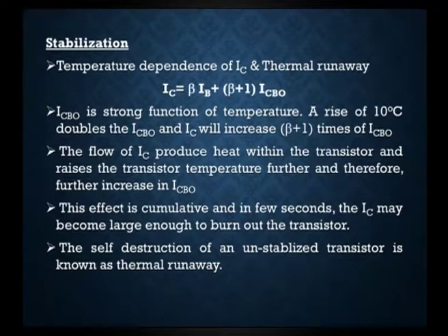The flow of IC produces heat within the transistor and raises the transistor temperature further, and therefore causes a further increase in ICBO. The increase in temperature again leads to an increase of ICBO, and the collector current also increases.